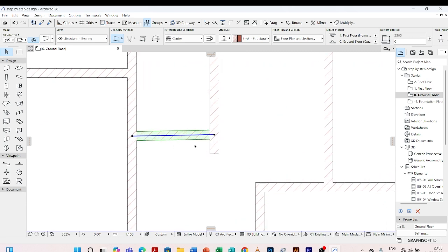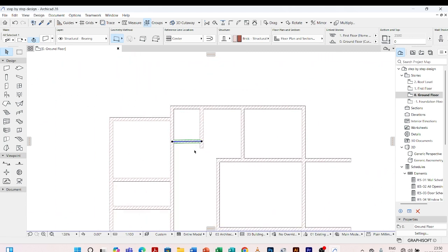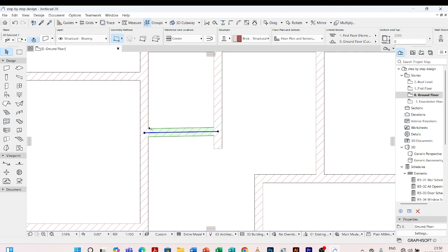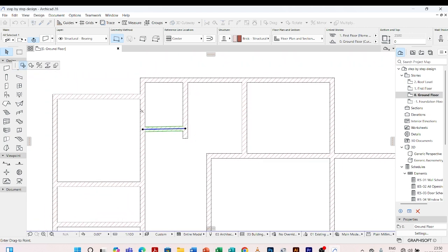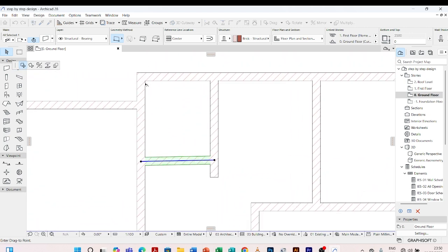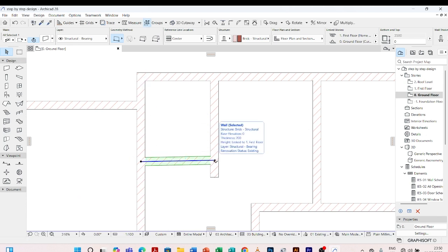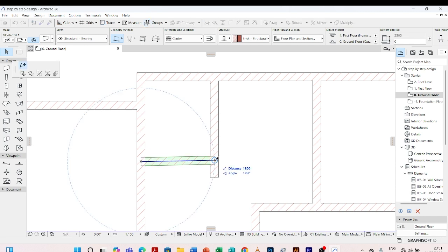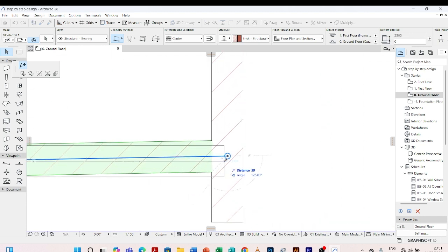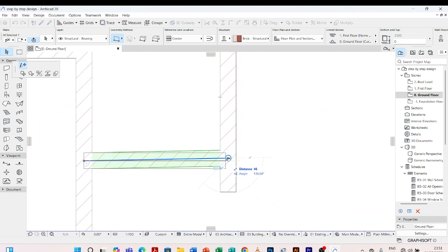This distance. Let me move it. I can either just come and click at this point. When I click at it, this one is dragging. It is already activated, so I can just drag. So I drag it, and this wall is not straight. So you need to adjust it. When it is not straight, you hold on to your shift, then it becomes straight. As you can see, it is now straight.